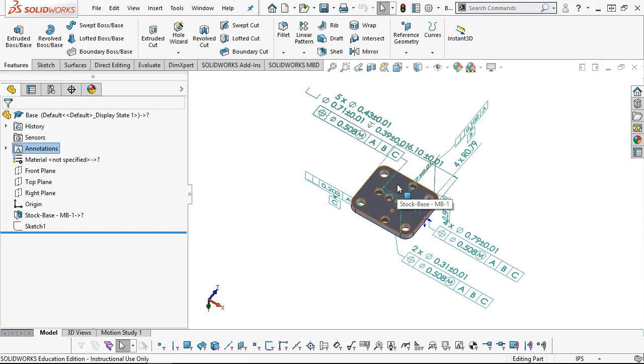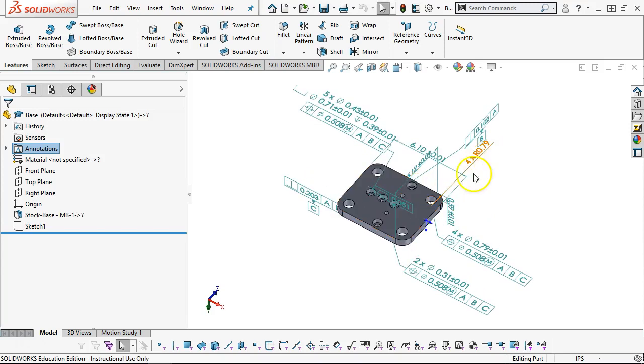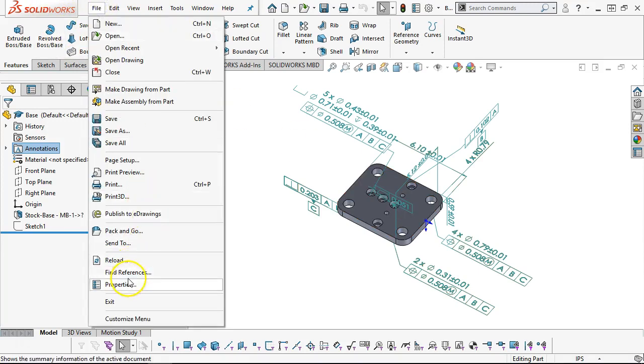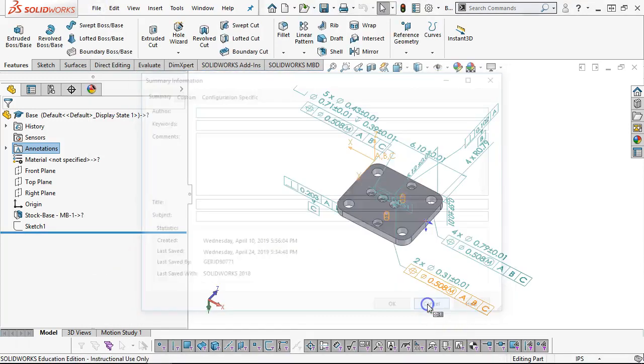My expectation was that we generate this, we modify it, and we now have something tied to the document. Even though we're focused on ASME Y14.5 2009, 2018 is going to allow this to be a working document. So if you've made these dimensions and we clean it up, with a little more management of the views, I could send this to a vendor and say, this is the document. This is our working contract. The dimensions, standard tolerances, I could put notes back into the file properties if I thought I needed them, and we could go from there.